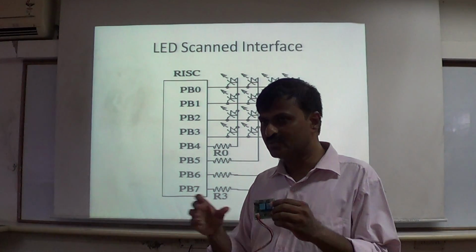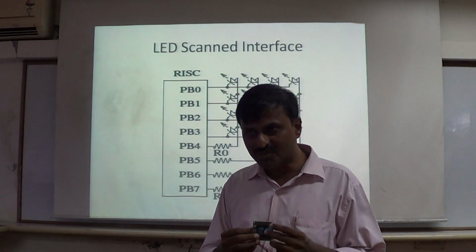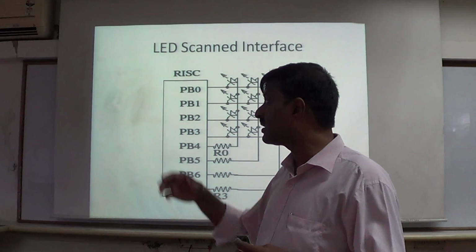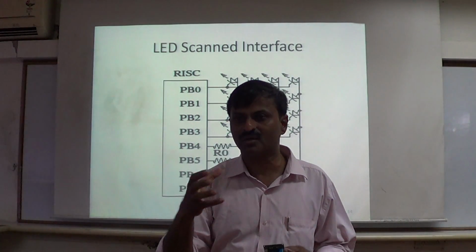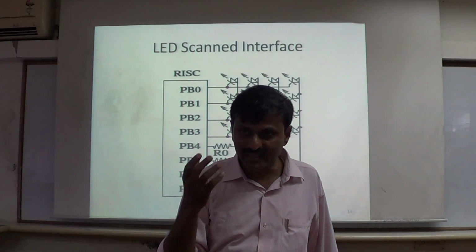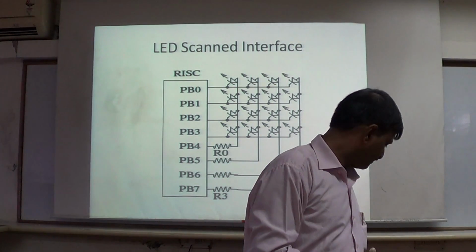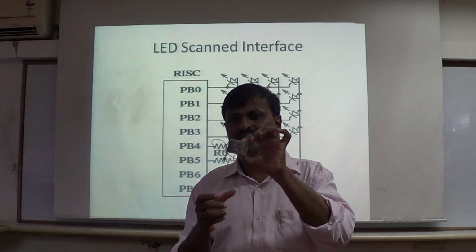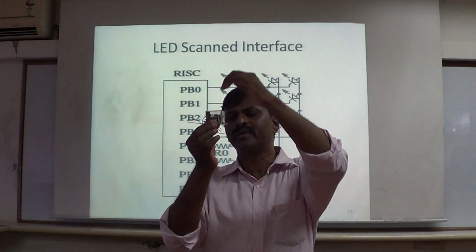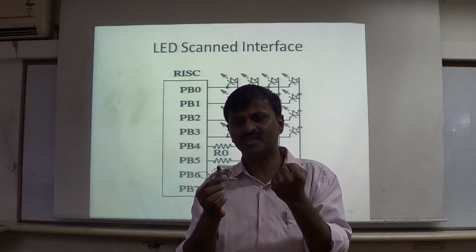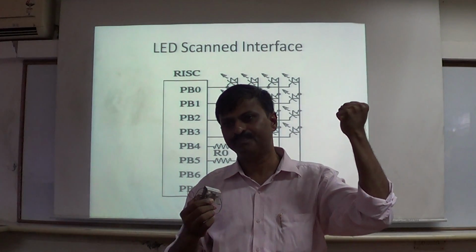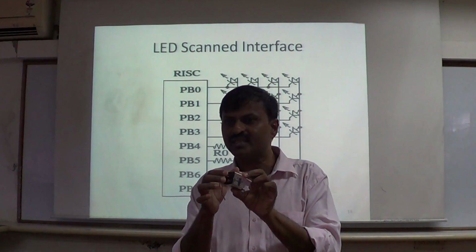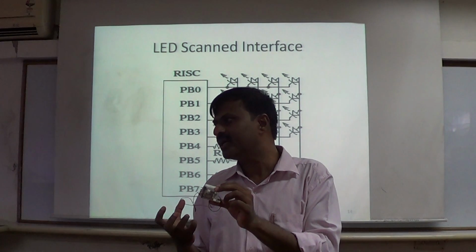I use relays. Whenever I have changed the direction, I use the relay. You can listen to the tick sound. Or in an air conditioner also you can listen to the tick sound. Refrigerator you can do that. It's a relay, electromechanical. There is a spring-loaded mechanism inside that relay. When it is not energized, this contact point is pulled down, and when it is energized, it will be pulled up. If it is de-energized, it comes back. So that means you are making or breaking the contacts by magnetic field.